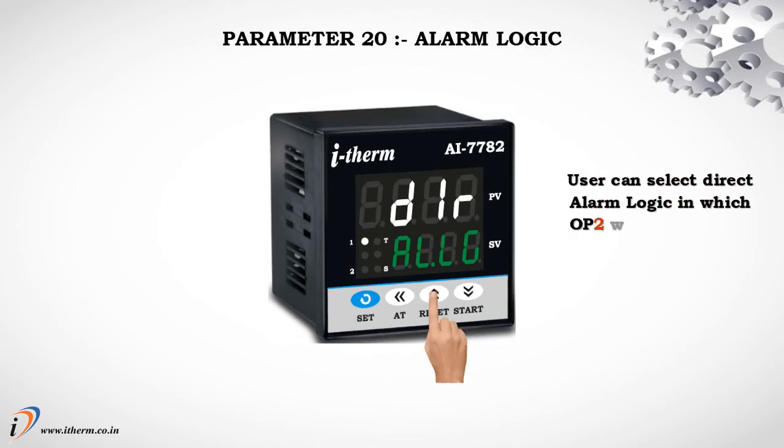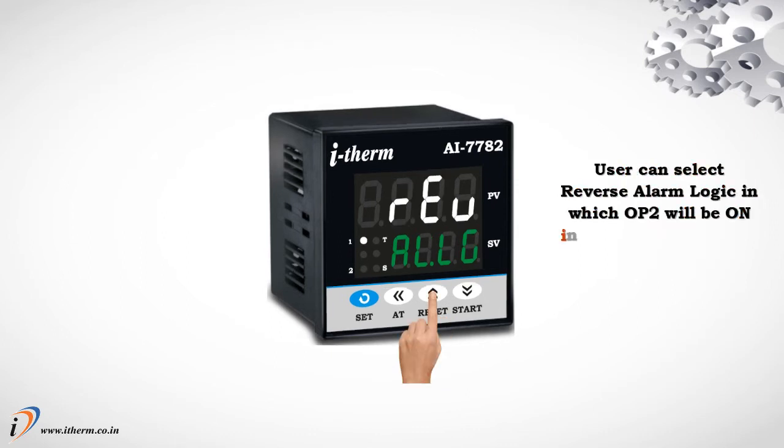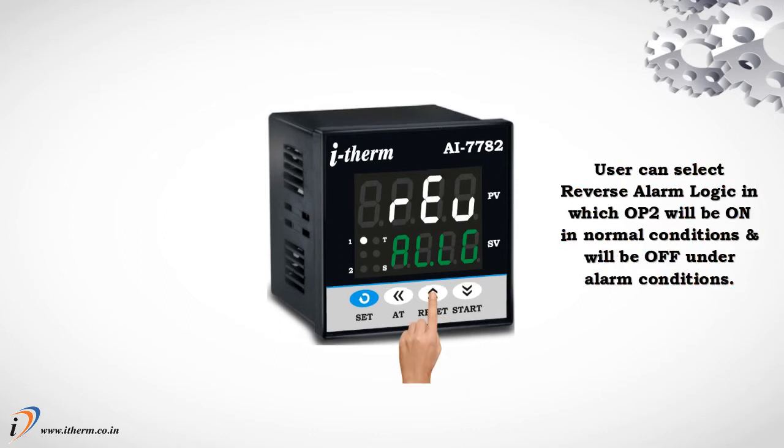Parameter 20, Alarm logic. User can select direct alarm logic in which output 2 will be on under alarm condition, otherwise off. User can select reverse alarm logic in which output 2 will be on in normal conditions and will be off under alarm conditions.